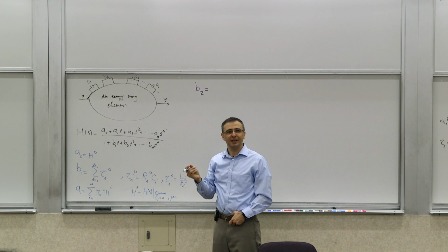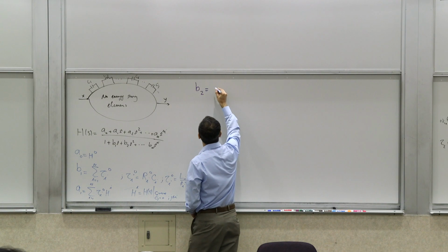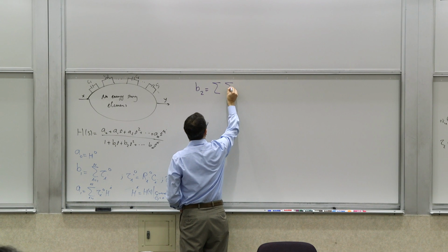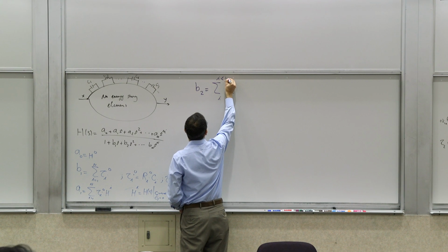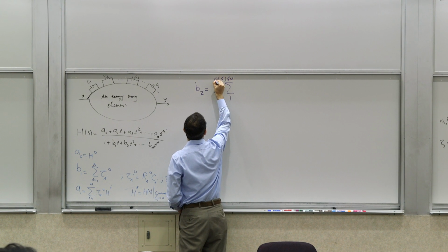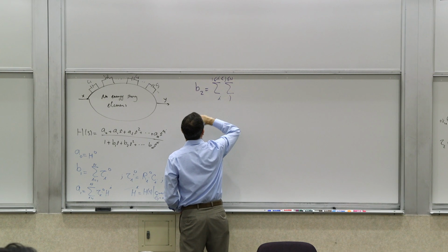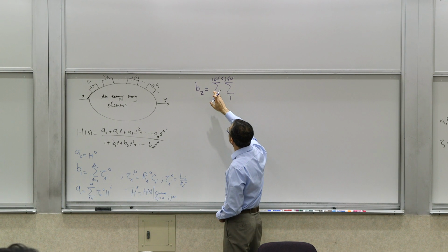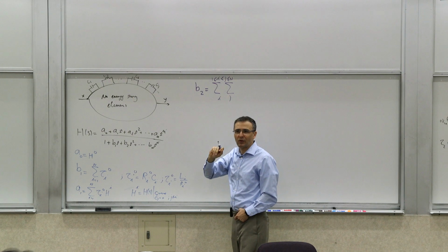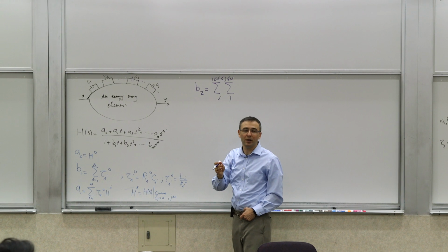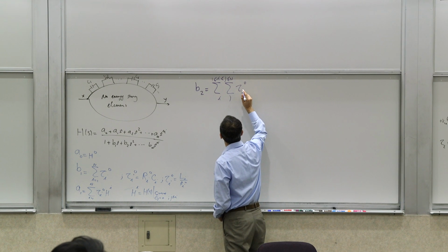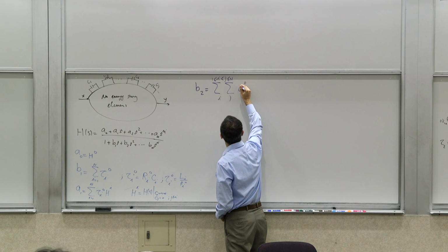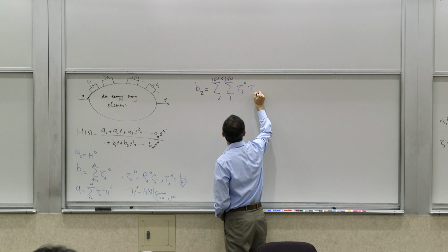So B2, I'm going to write the answer and I will explain what it means, is a double sum over i and j, where i is smaller than j, and i and j go between 1 and n, but they don't repeat. So if you have covered 1, 2, you don't cover 2, 1, of tau i0, which are the zero value time constants, tau ji.